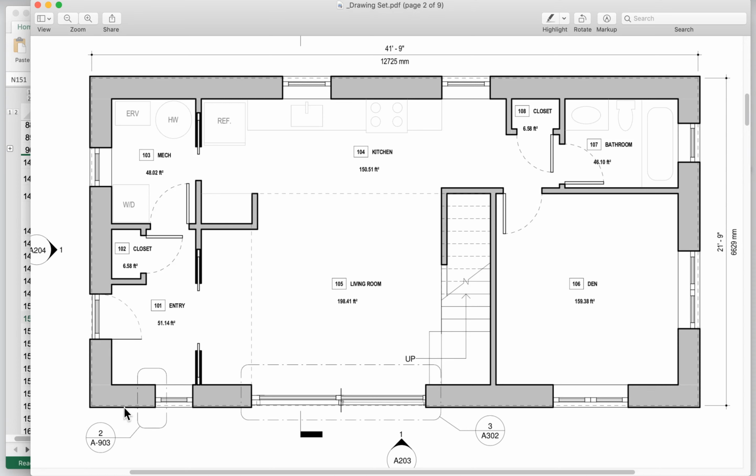We're going to look at those carefully and assess them. We're going to look at how the building is built at those corners, check to make sure we don't have any disruptions or lapse in our insulation continuity, and make sure we don't have any thermal bridges there. So I'm going to say those corners are going to be an important one. Obviously, the window installs are going to be an important thermal bridge.